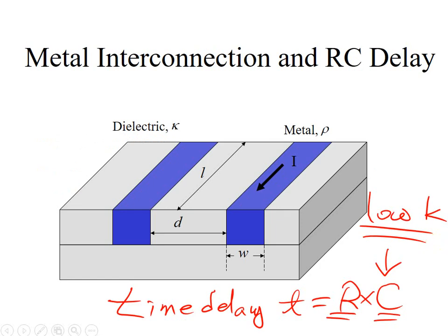Okay, in this section we discussed the basic devices of resistors and capacitors, and showed you how to simulate a physical resistor by way of dopant introduction into the silicon wafer in a specific area with specific depth. We call it sheet resistance, that means sheet resistors.